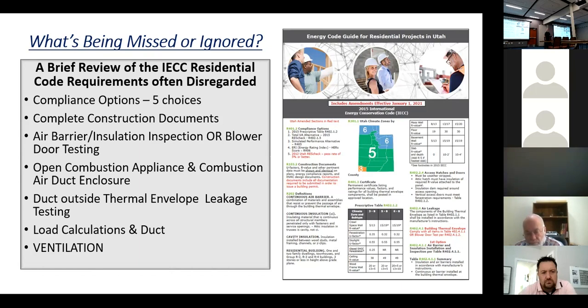Go to Alcoa Aluminum or one of the siding manufacturers and look at how much free area you get through vented soffit. It's almost nothing. It's like a couple of square inches per foot of material. And we have this requirement of one square foot per 300 feet of attic area if you have 50% low and 50% high. If you don't have that, then it's 1 square foot per 150 square feet. That's a lot of square footage.